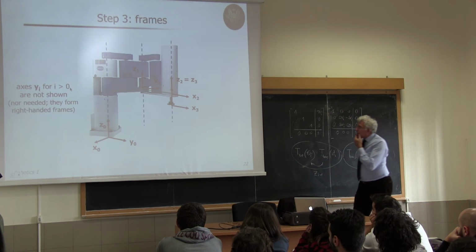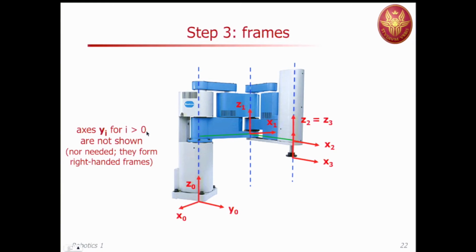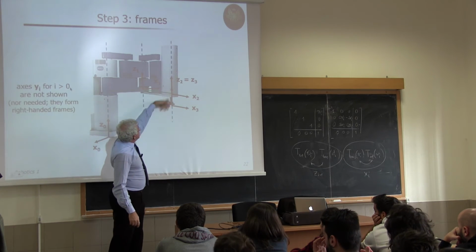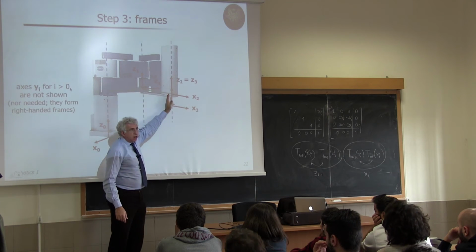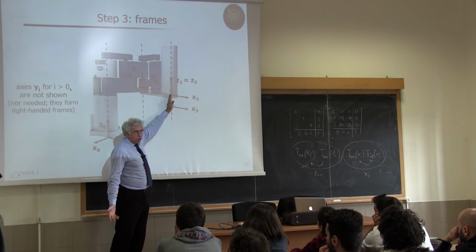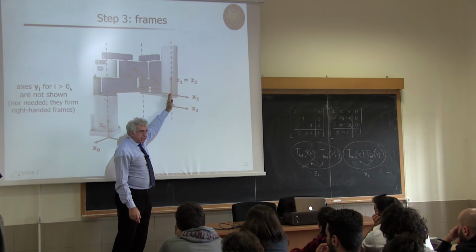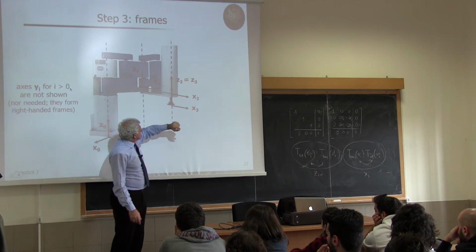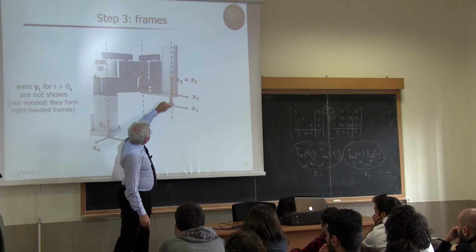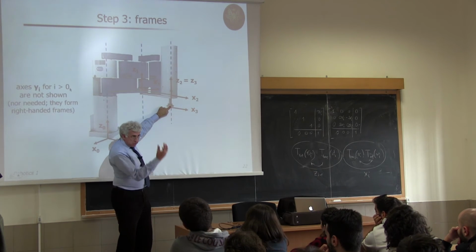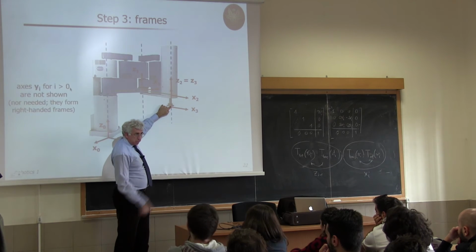Now the third frame. This is multiple arbitrary because it's coincident, no? So I can choose the origin of this frame where I wish. So z3 here is taken along joint axis 4, coincident and in the same direction, because I don't want to put a pi there as an alpha. Alpha 3 is still 0. Then the origin of frame 3 can be arbitrary. Now I place it here so I can trace exactly the position.